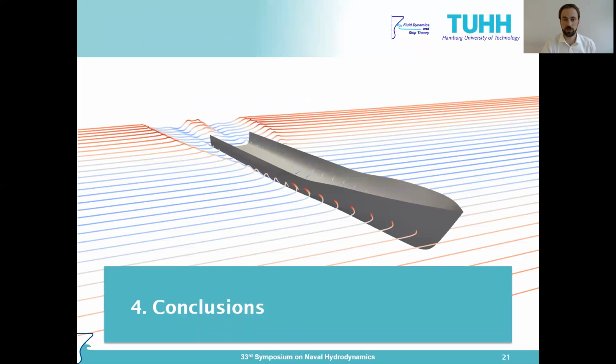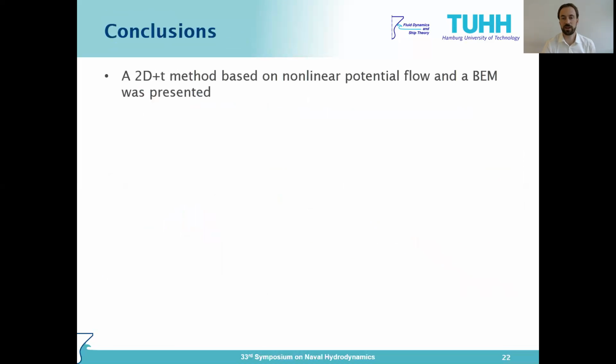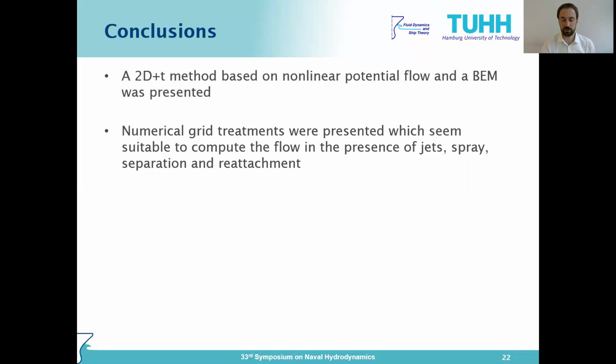So, which conclusions may be drawn from this investigation? First of all, we have presented a 2D plus T method based on nonlinear potential flow and a BEM, and we showed that numerical grid treatments are necessary to perform such simulations.